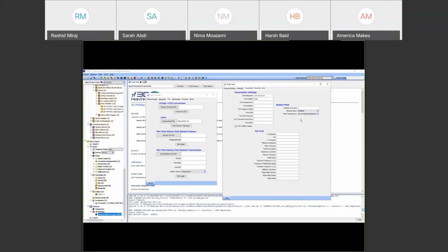And here is the visualization and setting parameters. You can visualize temperature, density, and other parameters. So let's go and have a quick look at the TMG output. We use 3D views in order to visualize the data that we generated by TMG. And in the TMG mode, you have different things to visualize. We have process map, temperature, void, thermal state, which is the thermal history, all 6 regions that my colleague mentioned in the slide: temperature, void, volume of solid, density, as well as conductivity, and also conduction, convection, and radiation.